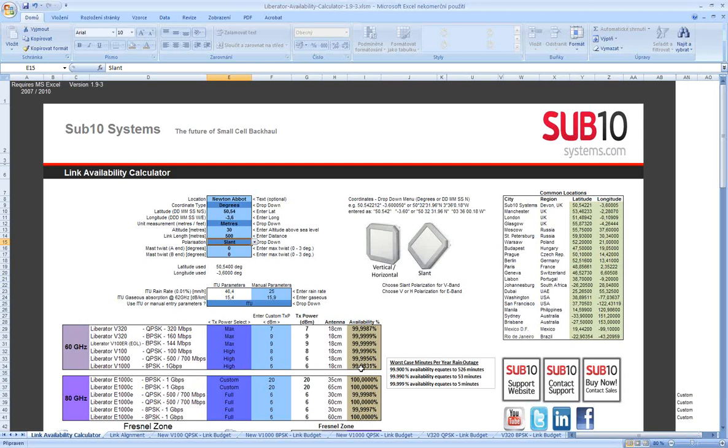Okay, look, the system is adaptive, it's capable of using adaptive modulation. This much time per year the system will work with gigabit, and if it's not gigabit, you still have a link which will be limited to only 700 megabits, which is 300 megabits less, but you have much higher availability. This is very important if people are looking strictly for gigabit: check, okay, but your distance is 600 meters, which is not doable with 4 nines, but we can design the link so it works 3 nines in gigabit, and the rest of the time will work with only 700 megabits.